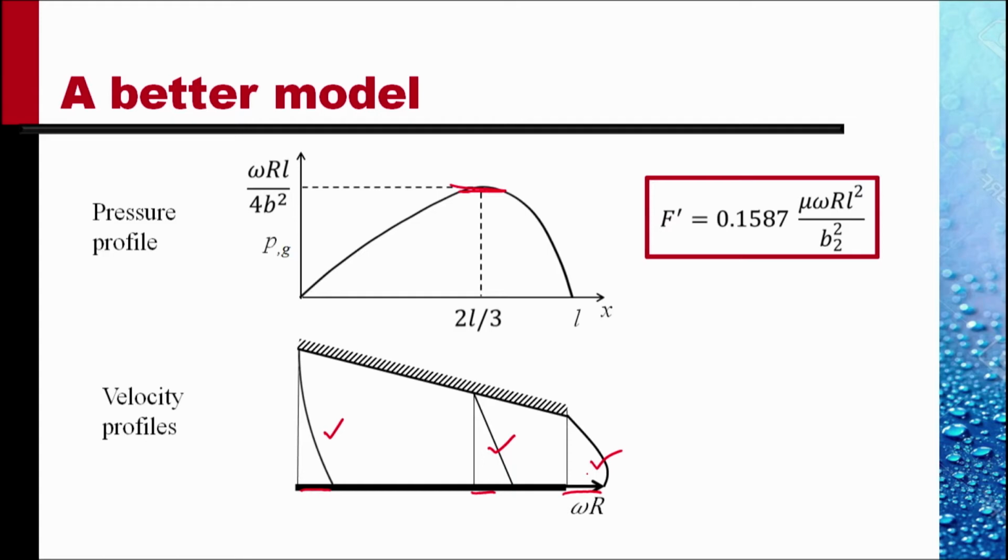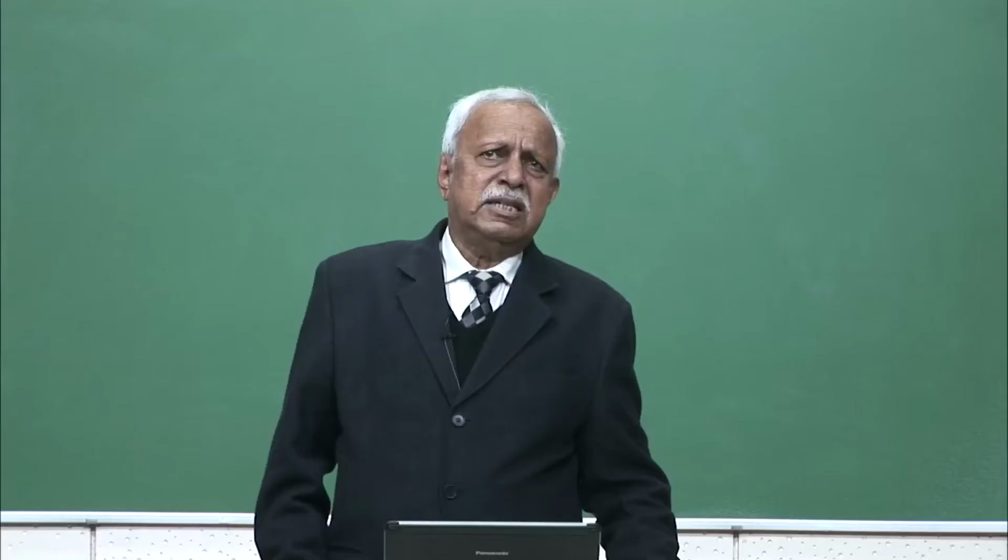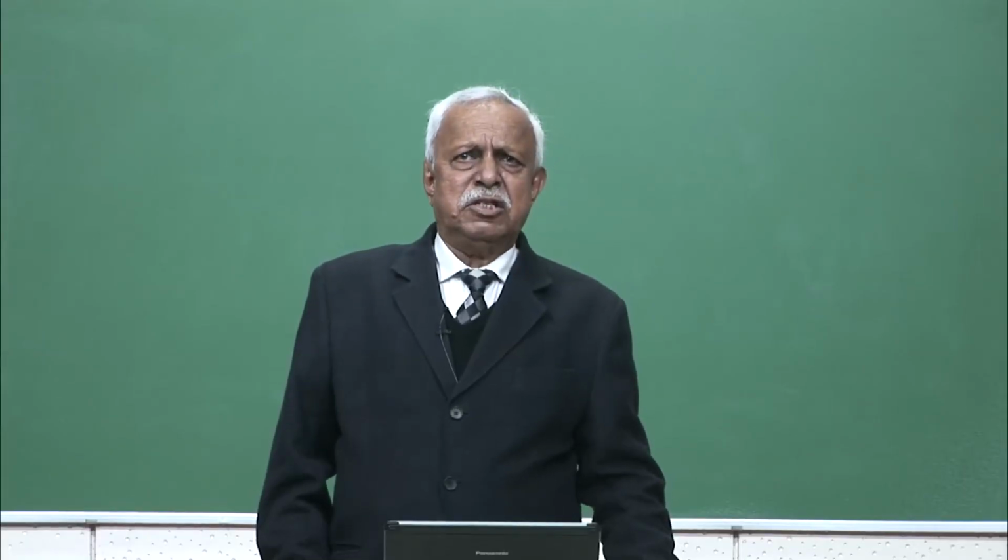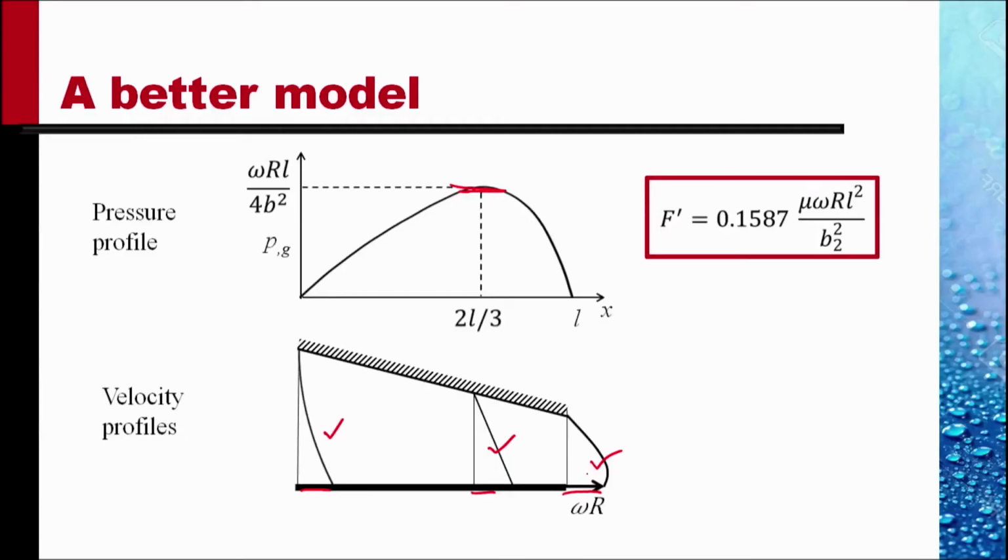Of course, we notice that F prime increases as mu increases. As the viscosity of the lubricating fluid in the bearing increases, the load that the bearing can support would increase. But there would be a cost. This larger mu would result in larger shear stresses, larger torques, and larger power lost in rotation.